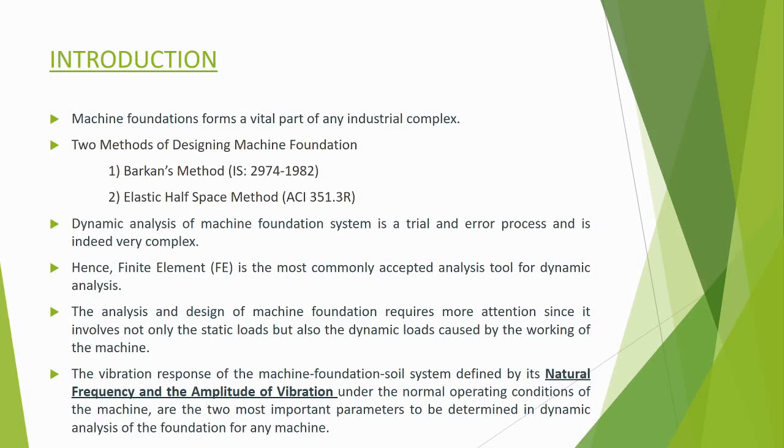There are mainly two methods for designing machine foundation: Barkan's method and elastic half-space method. Barkan's method is recommended by IS 2974 1982 and elastic half-space method is recommended by ACI 351.3R. It is an American code.